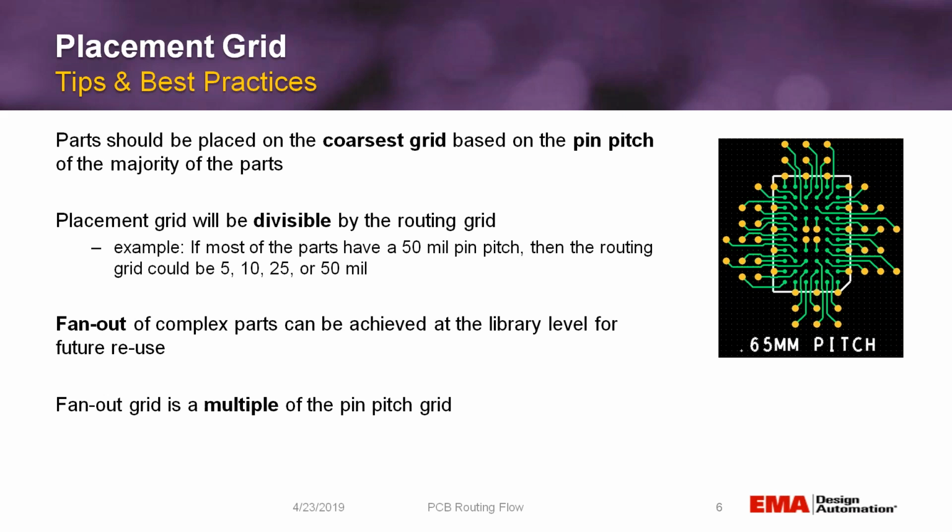This is really advantageous because what if I have multiple parts that use the same package? Once I figure out the pin escape scheme, I can incorporate this into the library footprint, and it has no effect on the schematic. In a lot of other tools, these vias would become another pin, and I would have to double the pin count of the symbol to accommodate that. We don't have to deal with any of that. We simply see this as a BGA with a via out, extended out on the end.